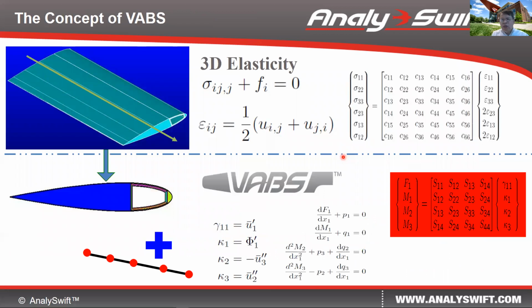To avoid the difficulties associated with these conventional approaches, we explore the slenderness, which is the smallness of the cross-section with respect to the length, to mathematically decouple the original 3D elasticity problem into a two-dimensional cross-sectional problem and a one-dimensional beam problem.